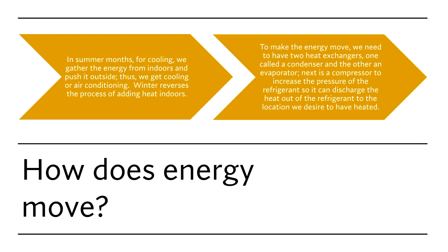All right, so in order to do the refrigeration process, we got to have a couple heat exchangers in this system. So we have one that's called the evaporator. That's the one where the liquid refrigerant at a low pressure is evaporated to a slightly warmer temperature. That goes to the other one, which is the condenser coil. And that coil rejects the heat into another spot, usually with much warmer temperature.